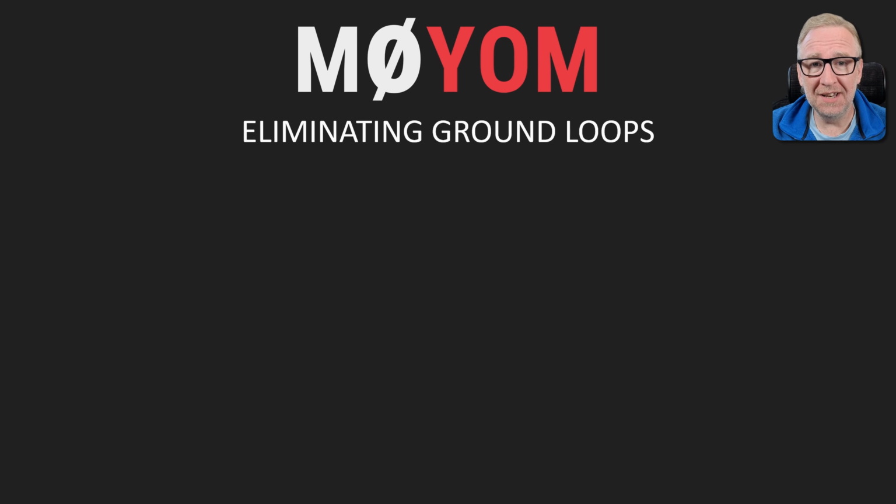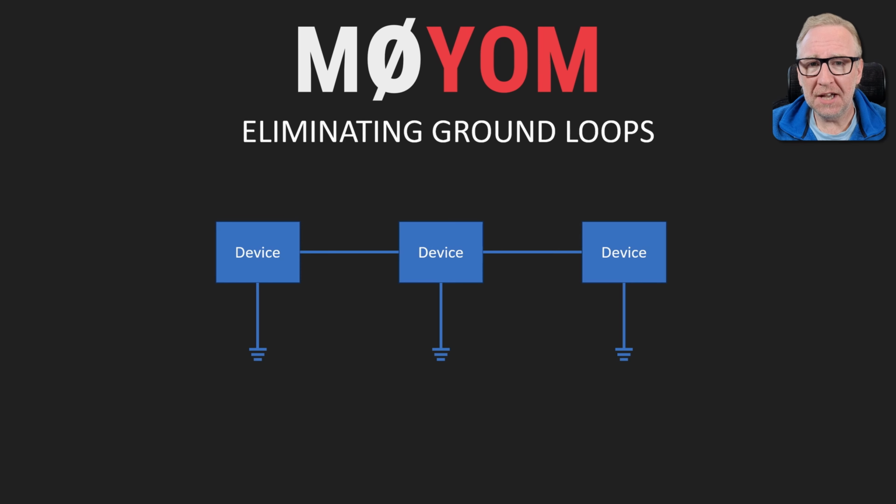Essentially, there are two ways that we can eliminate the ground loops. If we take another look at our diagram from earlier, we can change the grounding system to a star or single point ground like this. This results in only a single ground connection for all devices. Typically in a station ground, this is the approach that you should take, with a single ground bus being used for all connections. With our audio system, however, we're primarily dealing with the safety ground found in the mains electrical supply, so this isn't an option.